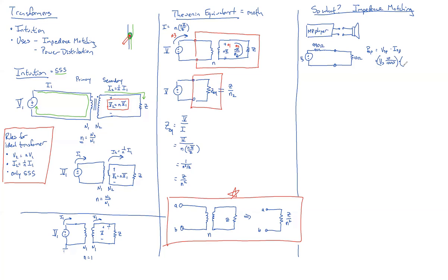And then we need to multiply by our I speaker, which is voltage over the resistance. Is it a current divider? Is current being divided through two different areas? No, it's just through those added together. So just VS over 1,000. So we've got something that looks like 10 VS squared over 1,000,000, or VS squared over 100,000.